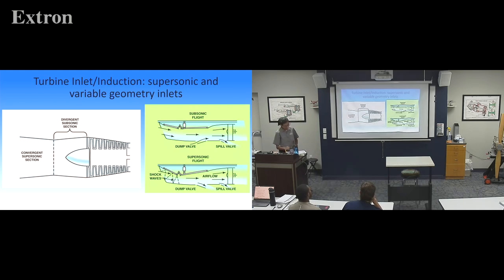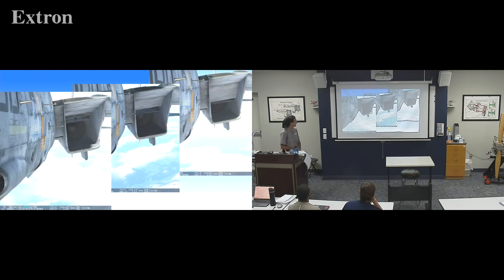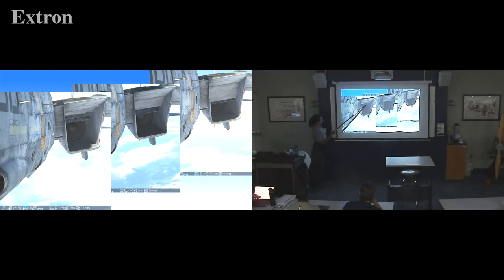And here is what it can look like, I believe, on an F-14. And here we're going, that has it in kilometers, 585, but you can see we're open as much as we can be. And then as he increases through transonic, it starts to close down, and then supersonic, now we've changed that inlet.